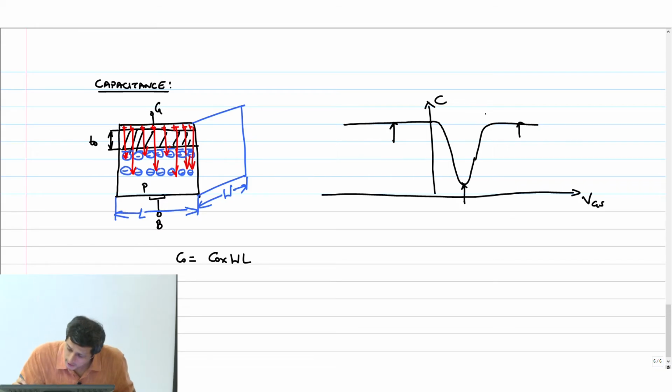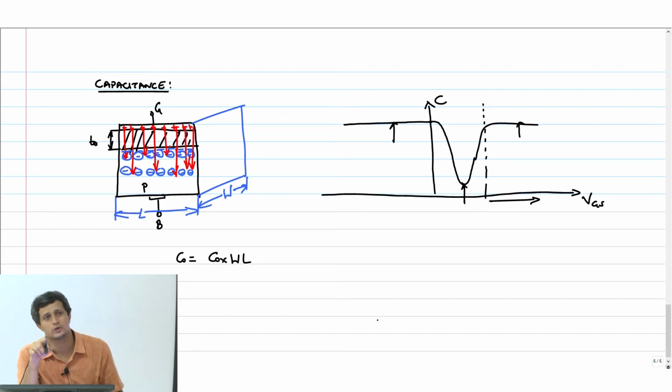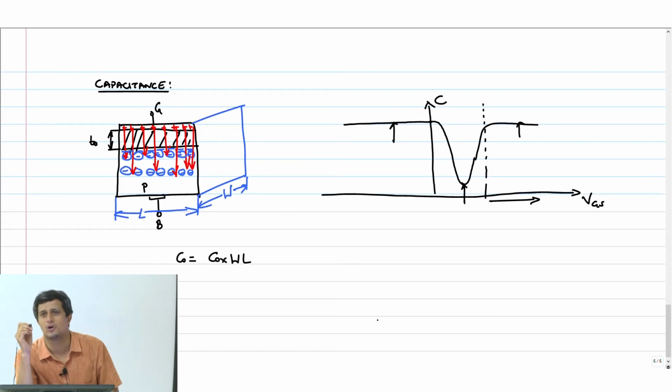So really, if you look at the region of operation, we are worrying only about the right of this region. Even in linear operation, what I don't want you to assume is that linear region means it's in depletion mode. No. When it enters linear region, the channel has already got inverted. That's how we have exceeded threshold voltage, right? Of course, it may not be as strongly inverted as it would be in saturation. That is fine, but still the capacitance is effectively this capacitance that we are talking about.